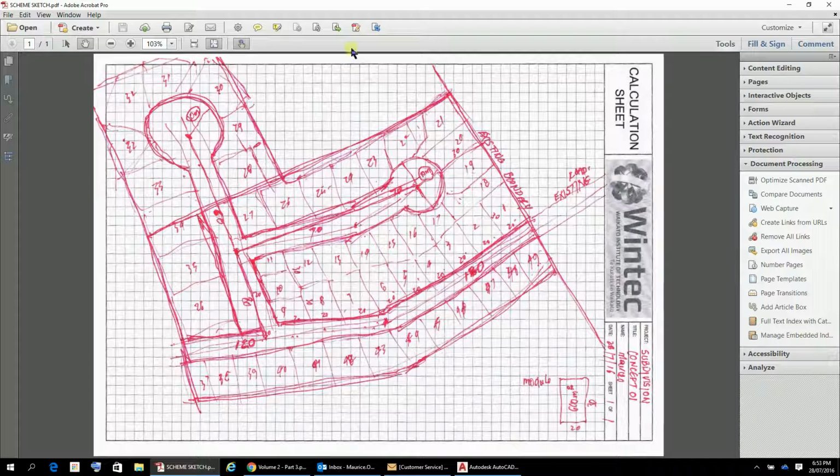So what are the next steps? Well, I think the next step is probably to confirm the typical cross-section of the roads that I'm going to use, because that will determine widths and things like that. Once I've come up with the typical cross-section, which I'll probably use one from previous examples, I will then start to draw up the layout based on that typical cross-section. Once I have the layout determined, then I will start to look at what sort of surface I want to put over that layout.